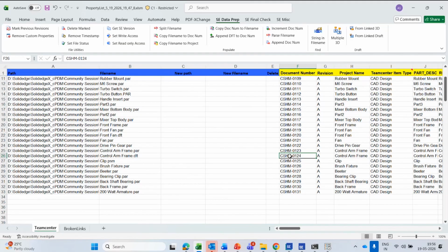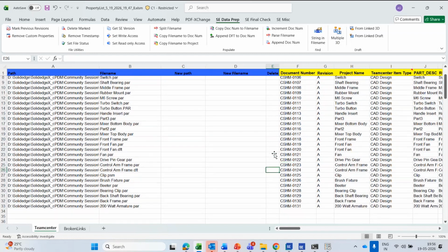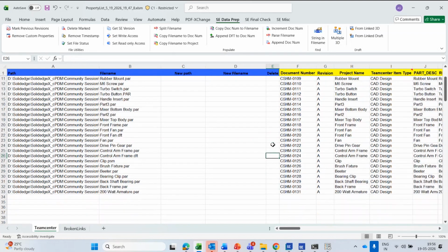That means on upload, the draft file will carry a different item ID and item revision. But that may not be my requirement here. In my case, I want to associate the draft file under the same item revision where my Solid Edge 3D dataset resides, that is, where the master resides.